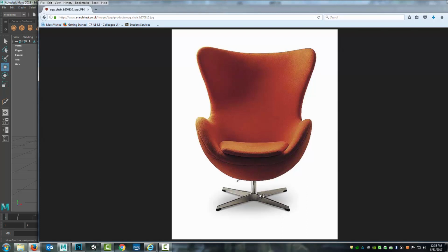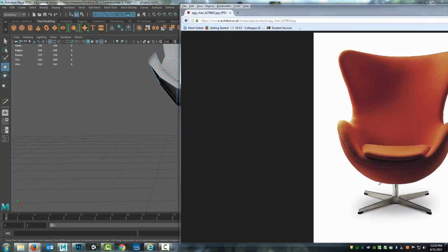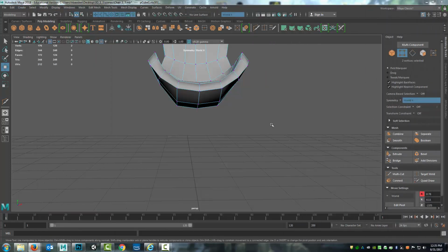Now, because I want simplified geometry, I don't want to add just a ton of information. I'm going to start by doing a cylinder, but reducing it to 8 sides. And what that will allow me is, as I come down to this shape on the bottom, there'll be the first face on the inside, the face that gets extruded, a face on the inside, and you see alternating, that gets you 8 sides.